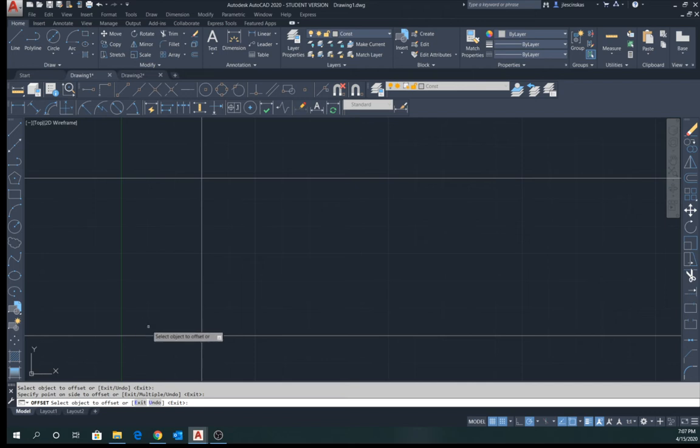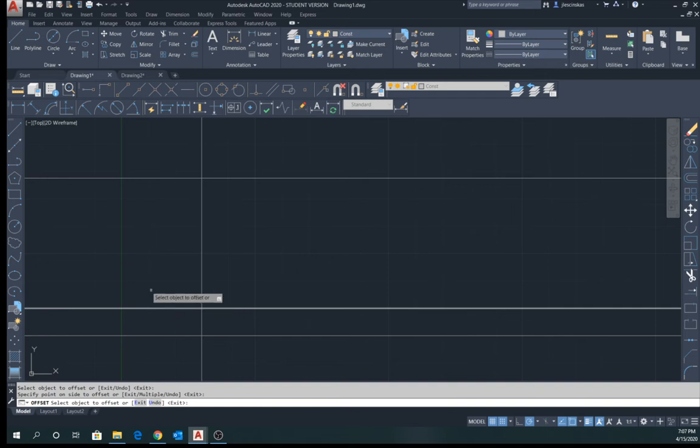Next thing we're going to do is start making all these horizontal lines. Now, from this first horizontal line, there's one line that's measured 1 inch up. So we'll add that line in. Again, offset, come down here, type 1, enter, click, make sure we're moving up, and that puts our line in. And there's a second line which is 4.5 inches up. So we do the same thing.